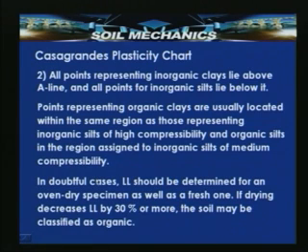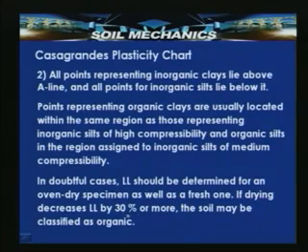In doubtful cases, sometimes we will get a doubt whether the soil is really inorganic or organic. So, to verify that, it is suggested to carry out a liquid limit test on a fresh and then an oven dried sample. If the drying decreases the liquid limit by 30% or more, the soil may be classified as organic, because during the drying process the soil may be subjected to some irrecoverable changes. So, because of that it affects the liquid limit.